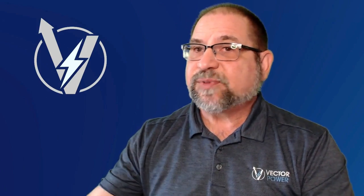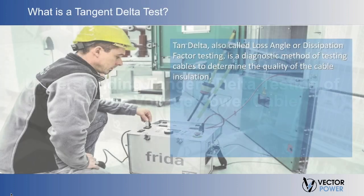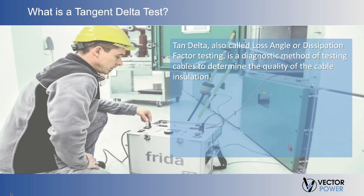And in today's presentation, we are going to dig into the intended purpose and the theory behind the tan delta test as it applies to medium voltage electrical power cables. Now, tan delta, also called loss angle or dissipation factor testing, is a diagnostic method of testing cables to determine the quality of the cable insulation.